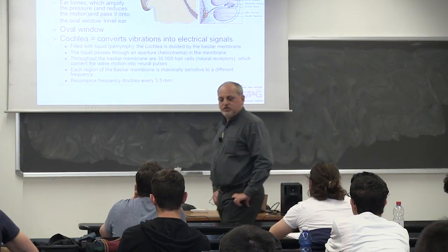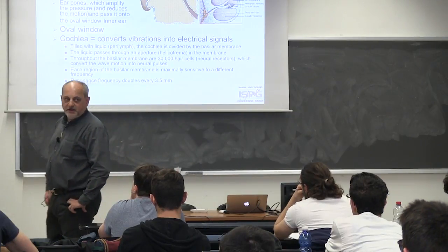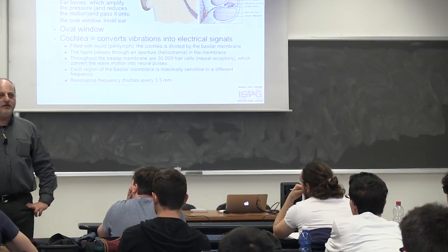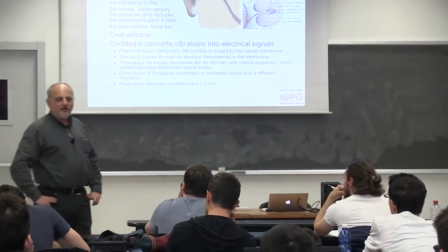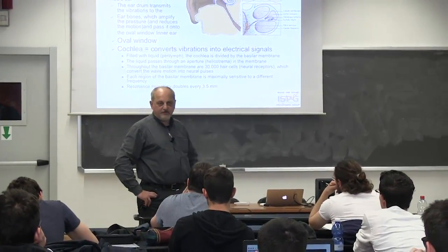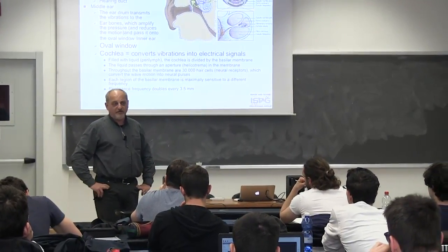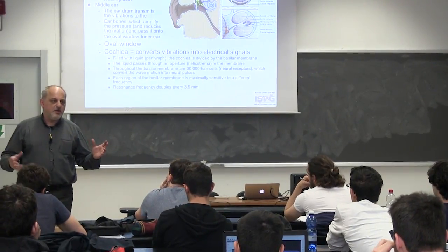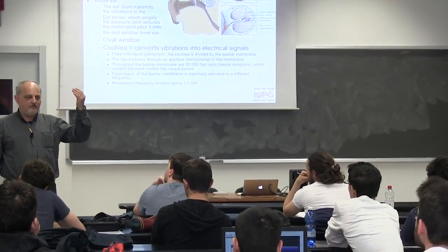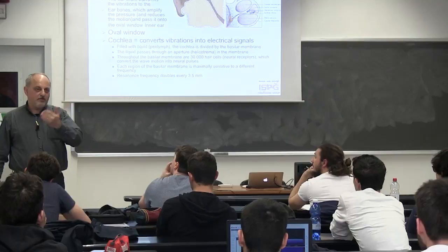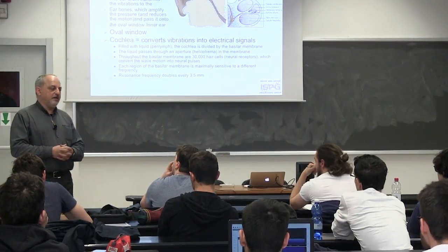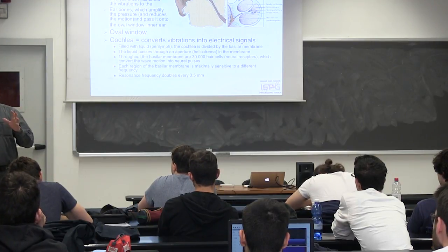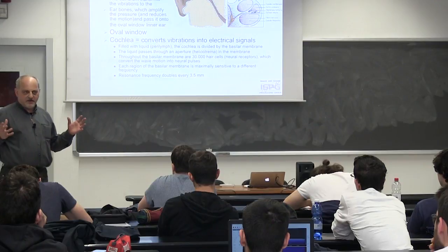Are you familiar with the notion of a transformer in electrical systems, right? You know that a transformer is a nearly transparent electrical object that transforms voltages and currents in such a way that their product remains constant, so it will have constant power, so you don't have loss of energy in that operation. But you start, for example, from high voltage and low current, and you go to low voltage and high current, for example, just to give you an idea. So it's a nearly transparent object that does a conversion without being lossy in this operation.